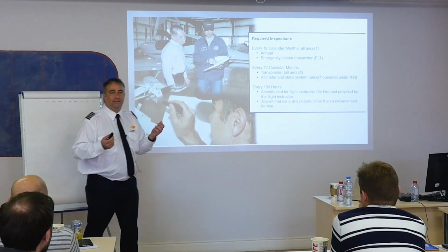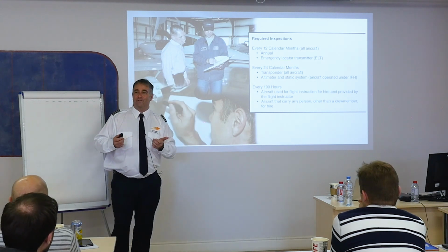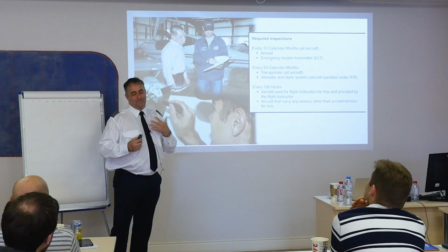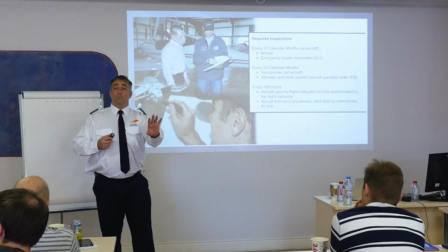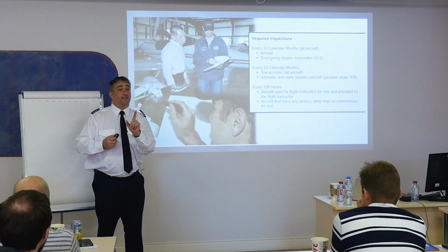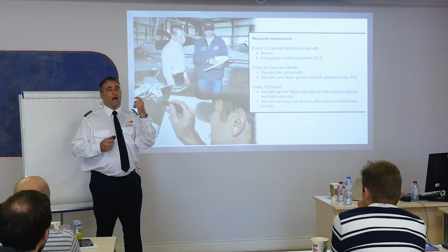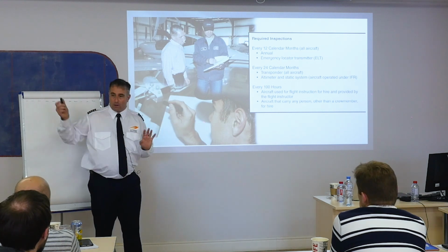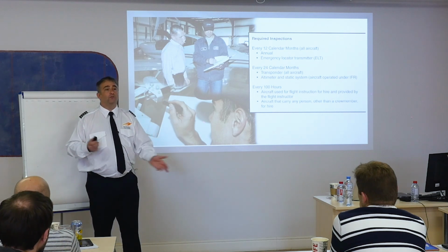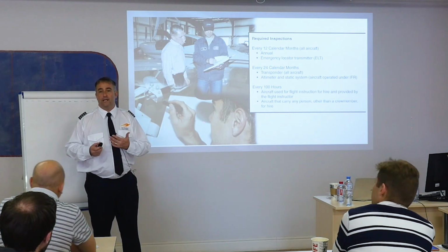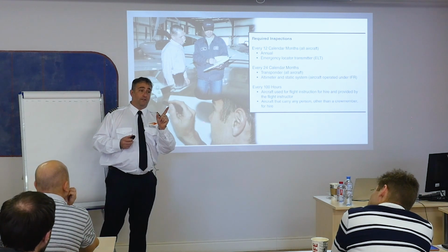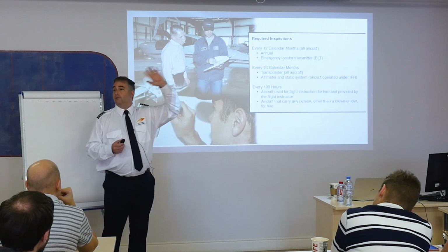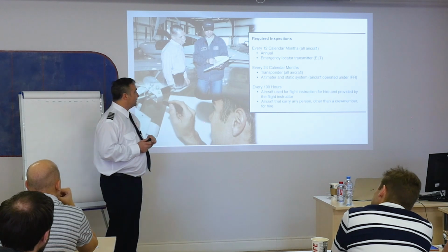Next gen is a kind of cool thing that's happening with our airspace system. It's going to put all of ATC, most of ATC, out of a job. Yes. You can tell my bitter likingness of ATC. But phase 1 was a mode S transponder, which means that our registration is transmitted to the ground. It's transmitted in all directions, but it's transmitted by anyone that's receiving that. So mode S transponders became a requirement for civil aircraft in the United States January 1st of this year. So we have to have that, and it's required for an inspection every 24 calendar months.